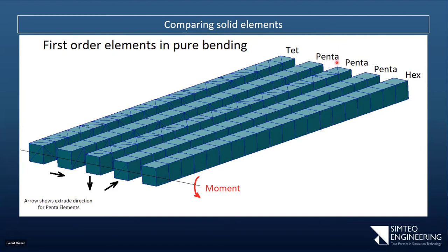Okay, the second one is the penta mesh. So the penta mesh, there's 3 of them, and I've created them by taking a tri-mesh on one specific face and then extruding in a specific direction. So in this case, it's a triangular face there. The front and the top in this case have quadrilateral faces, and the 2 sides don't have any. If I look at this one, I've meshed the top using tris and then extruded in the thickness. So all of these are in this plane. This one, I've meshed the front with triangles and then extruded in that direction.